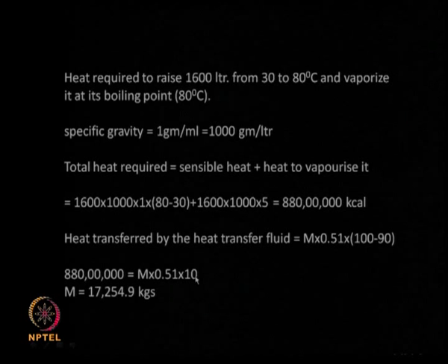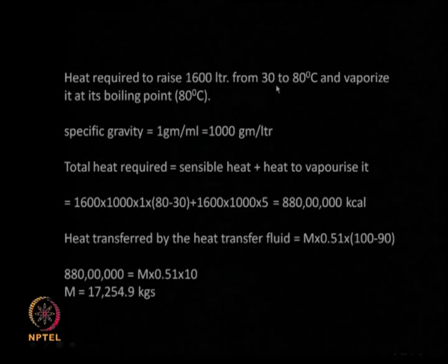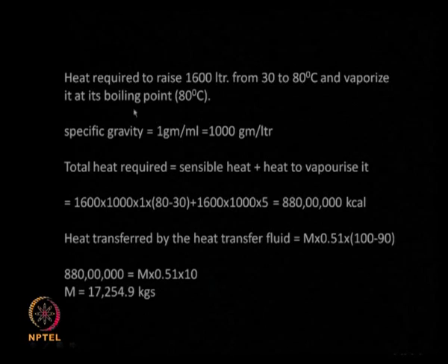So m will become, you divide by 10, you divide by 0.51, you will end up with this particular number. If you convert that into kg, you will get 17,255 kgs of heat transfer fluid is required to heat a fluid of quantity 1600 liter from 30 degrees to 80 degrees and then raise it into its vapor, okay. So this is a typical heat balance problem where you are balancing the heat